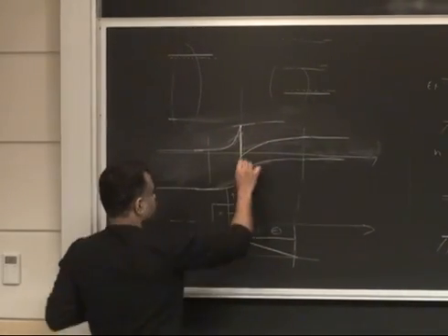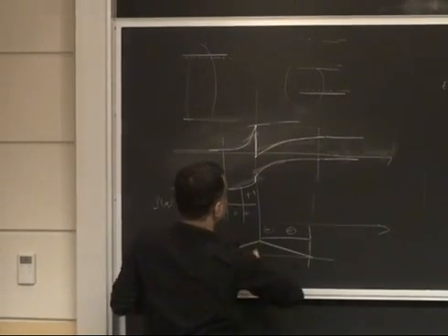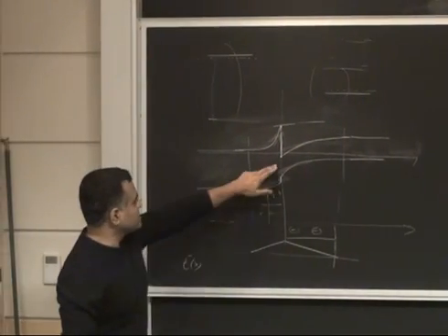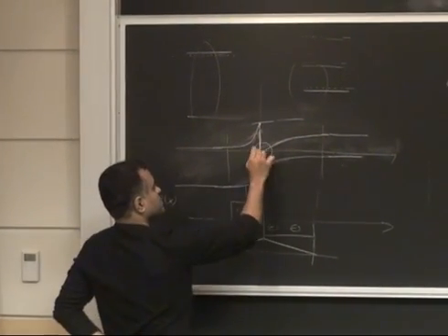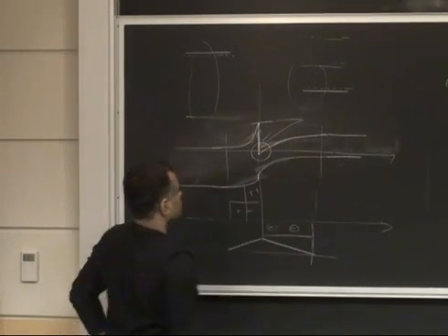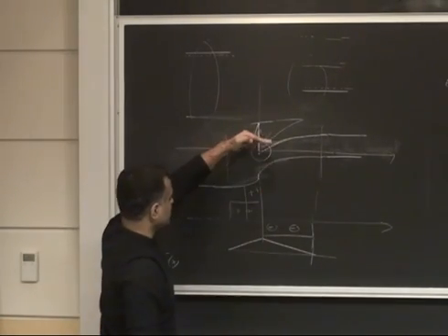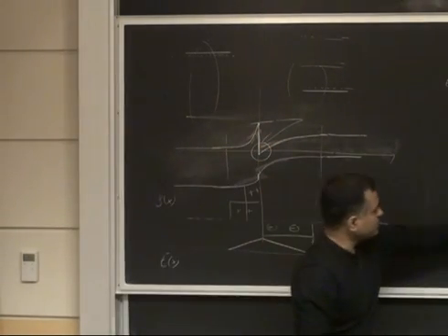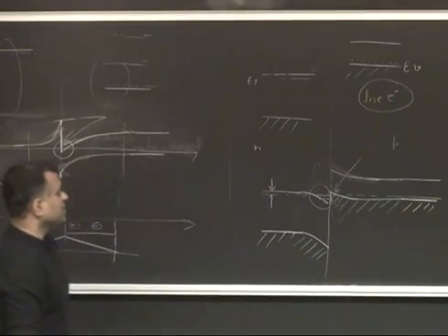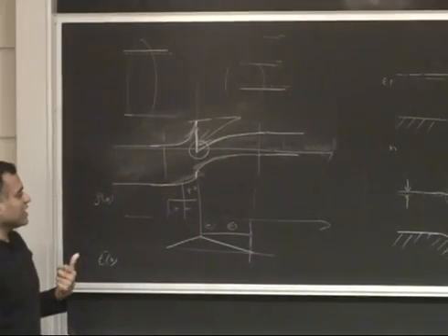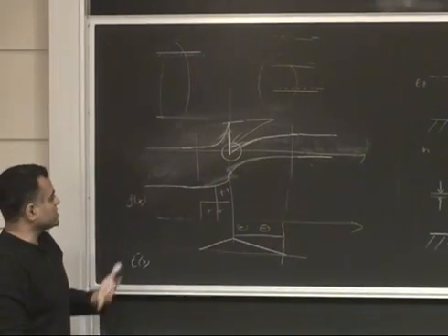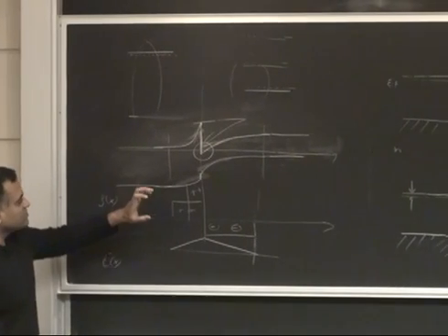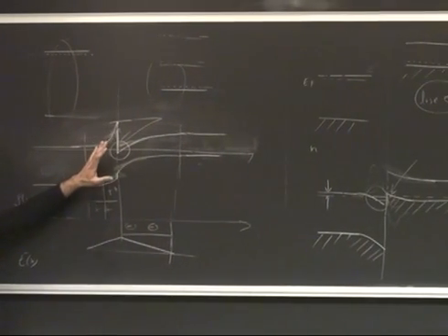As long as there are no regions where the Fermi level goes into the conduction band, or the Fermi level goes into the valence band on this side, for example, you don't need the Schrodinger equation to solve this problem, because it's mostly semi-classical. Poisson equation works well.